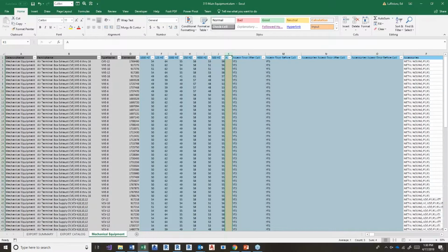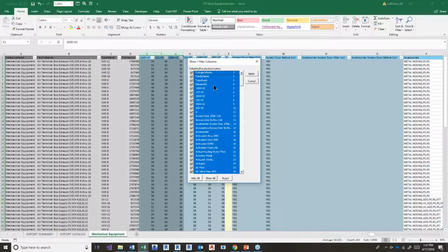So I'm just going to delete that. There's no harm in deleting a parameter in here, as long as we're not going to re-import its value. You just want to avoid deleting some of the critical fields in here like element ID. And if you were to scroll all the way to the right-hand side, there would be a GUID that we don't want to delete because the software is actually using that. But for any given parameter, if it doesn't exist on import, it simply won't get imported. So now I'm going to come up, and now we can see all of our parameters, all of our columns.